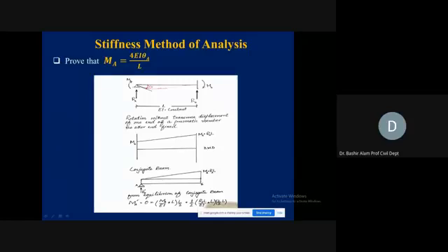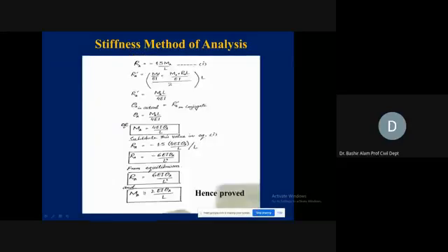It will be simply the load of this rectangle plus the load of this triangle, which will be MA divided by EI times L plus half of RAL over EI times L, which is the area of this triangle. So if we add them up, that will become equal to RA prime.